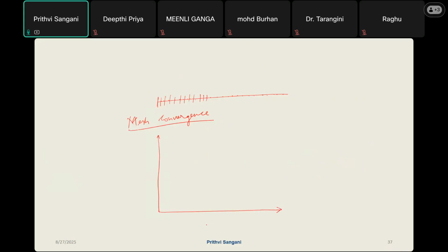On the x-axis, you will take mesh size as your variable, and on the y-axis you can take any output variable, usually deformations, or maximum S Mises, or S11, whatever it is. In the current case, let us take S11 as my Y axis and mesh size as my X axis.